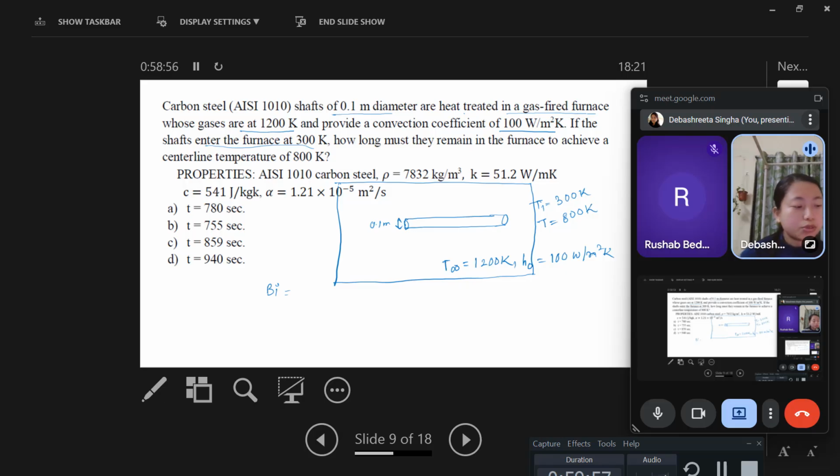I said it beforehand, it's lumped method, but for finding out the time duration and all, you can start thinking in this way that it can be lumped model. So for finding out whether it is lumped model, you need to find out the Biot number at first. So it is given as hL by k.